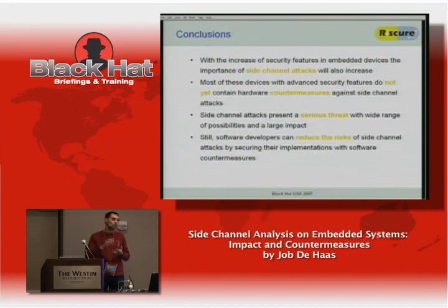To trigger, and so on. Those complications are the ones that you don't see in a smart card, because in the smart card you send it I/O, it happens, you trigger and you measure; it's clearly defined. In an embedded system, the obstacle is often getting the crypto with the key to actually happen at a certain moment in time with known data that you can extract.